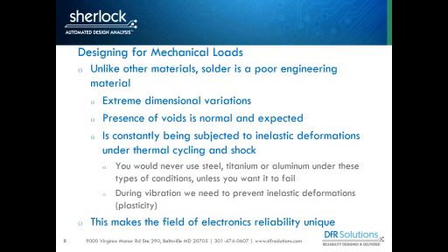This is one thing I like to stress during any of my presentations: unlike other materials, solder is a very poor engineering material. It's not dimensionally accurate. We're squeegeeing out paste, and so we get a lot of geometric variation. And one thing we'll talk about a little bit later on is that small changes in dimensions can affect stress states dramatically for high cycle fatigue.